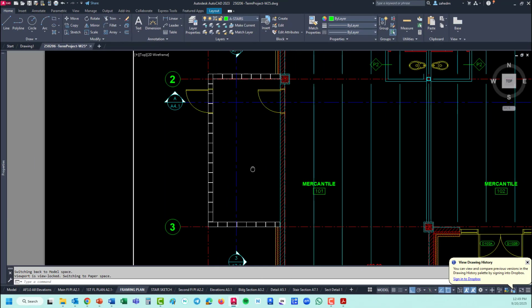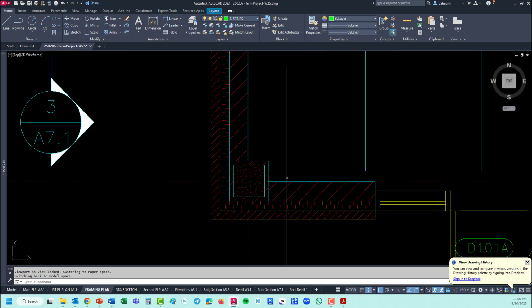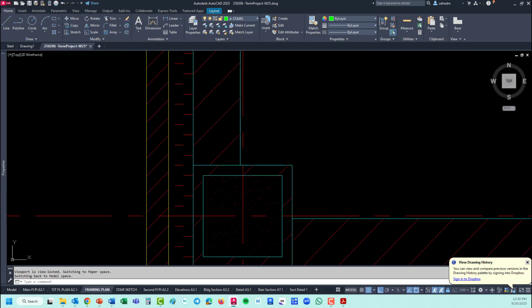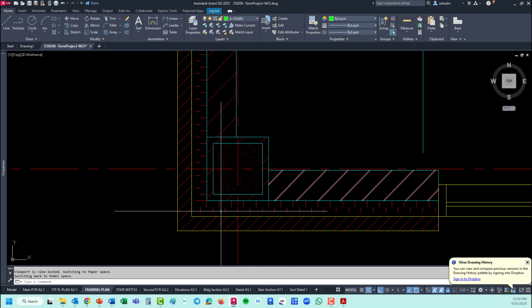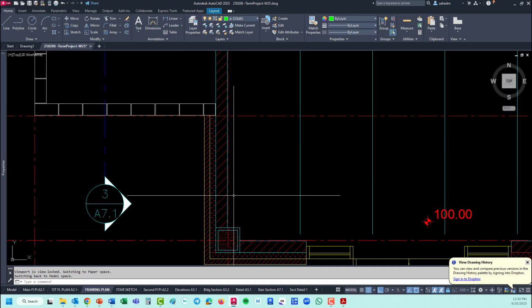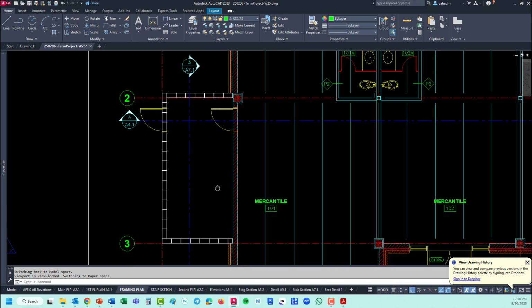Okay, so here is the situation that we have all the blocks laid out around where we want to put it. The relation between the grid line here, grid line number 2, with the block is similar to the grid line B as we've been discussing it in our sessions, 10 millimeters away. So the face of the concrete block to the grid line is 200, and this is how the pillars are sitting in the corner of the building. We'll get to the building envelope later on. We discussed that in class, but that's not the topic we are discussing in this tutorial.